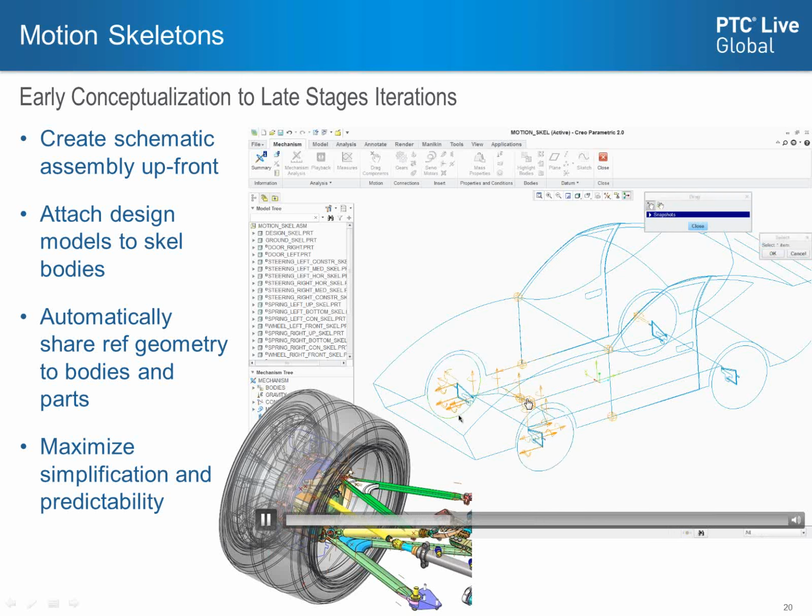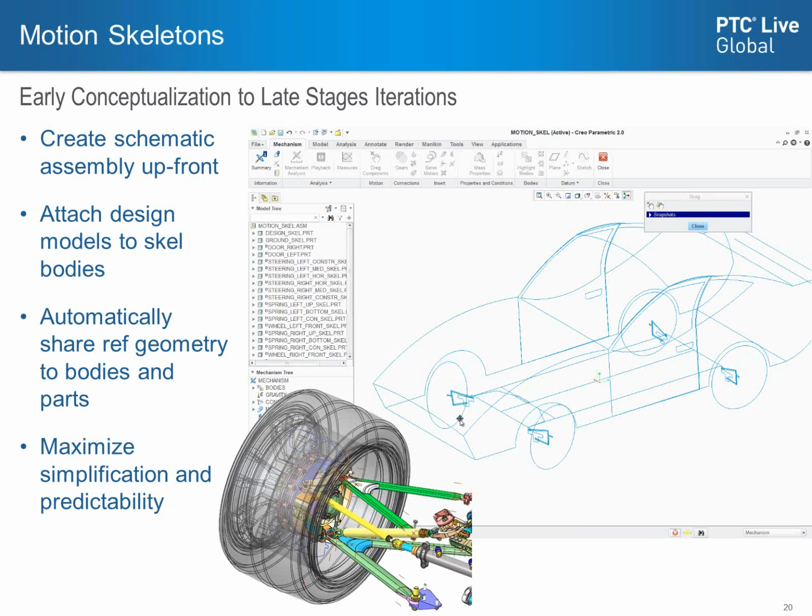Creo can automatically detect by certain logic these contacts between the curves and suggest the user automatically with different kinematic constraints between the different skeleton bodies it is defining. Usually when two curves have a mutual corner, Creo would suggest to identify this corner as axis or as ball joint and so on. User can of course change this definition if the automatically detected one is not suited. In most cases it would be more or less like sketching on a napkin. Creo would typically suggest exactly the type of connection that the user meant to have.